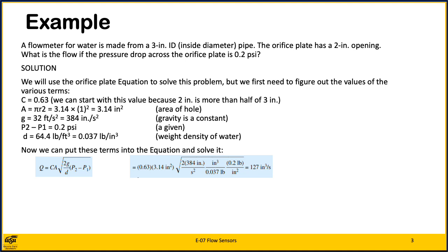To make this a more accurate flow meter, we would have to measure the flow with some other reliable flow meter and then adjust C in the equation to make the readings consistent with what we know them to be. So what you could do is use that pipe to fill up a 10,000 litre tank and time that, and then you could recalibrate the flow meter.